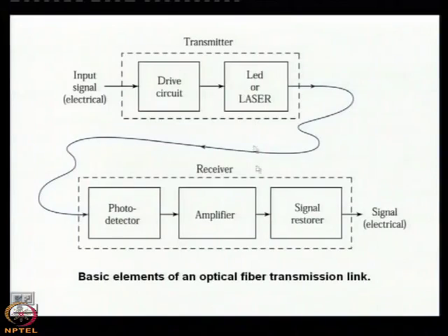Okay. Another thing you know that the receiver portion, I was talking about the transmitter portion, now this is the receiver portion. In the receiver portion, you see that the light comes by this fiber optic cable by the process of total internal reflection in the optical fiber. In the receiver station, you see that there is a photo detector, right. So, remember, first we converted our audio signal into electrical signal and then to optical signal. Now, we shall do the reverse thing, because if some light comes in front of you, can you say what is there inside the light? You cannot say.